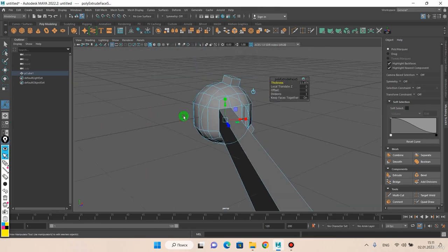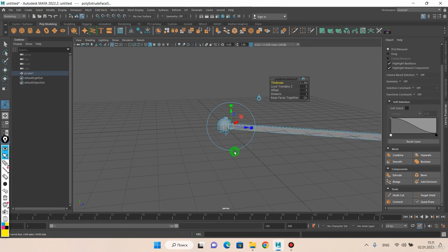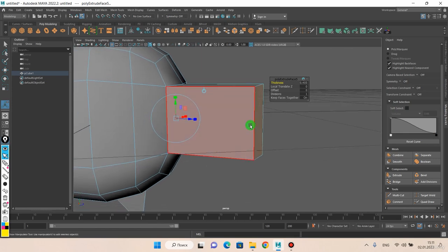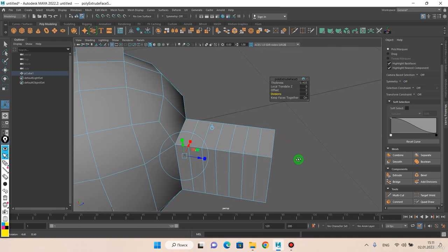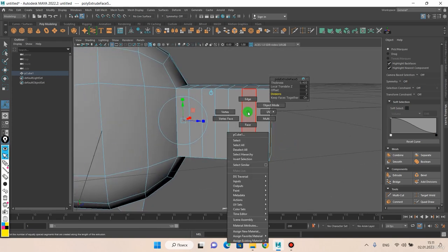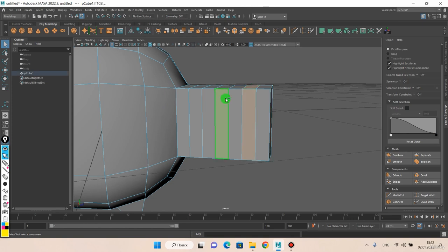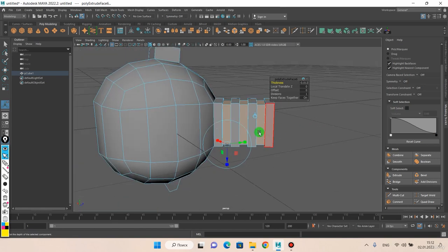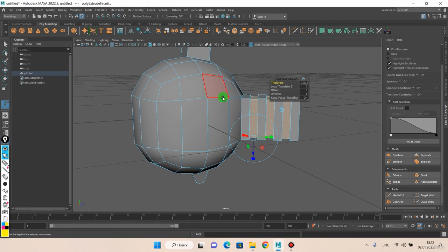So let's move on to the next parameter, divisions. Here, as I said, you need to use Control and Control Shift to slow down the manipulation. Divisions is pretty easy. You can create as many divisions as you want across our extrusion, and you can use these divisions to add some details into your model. For example, it can be a grip on a knife or basically anything.